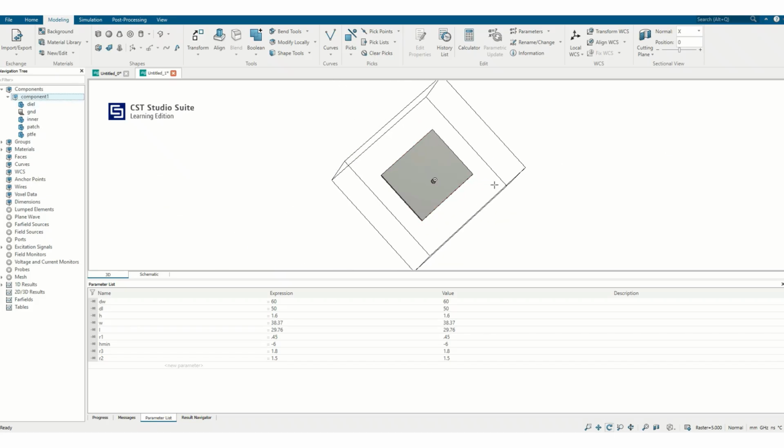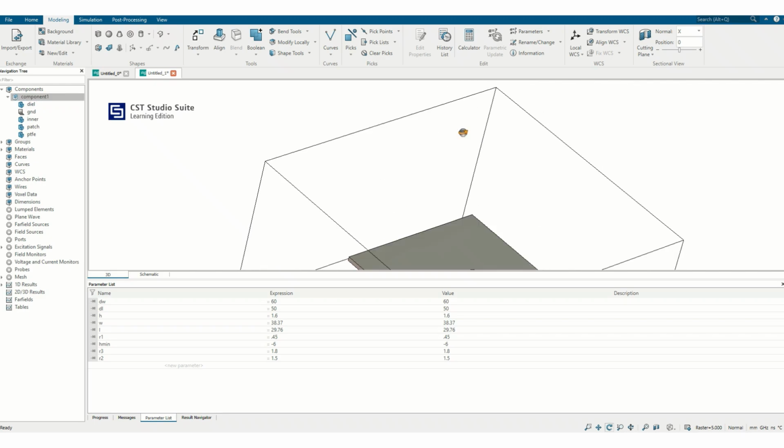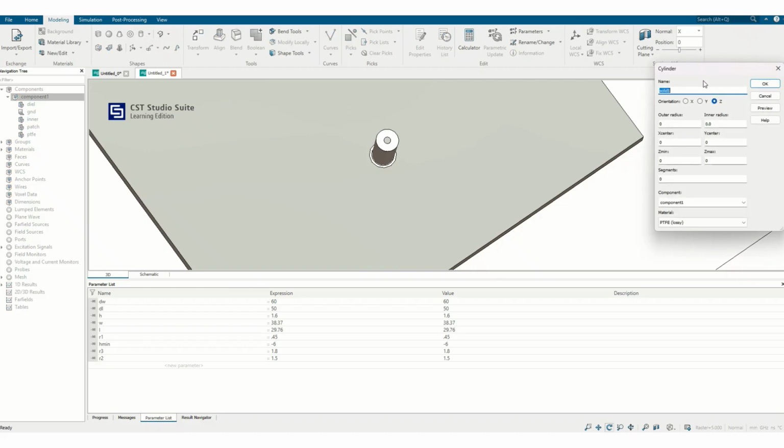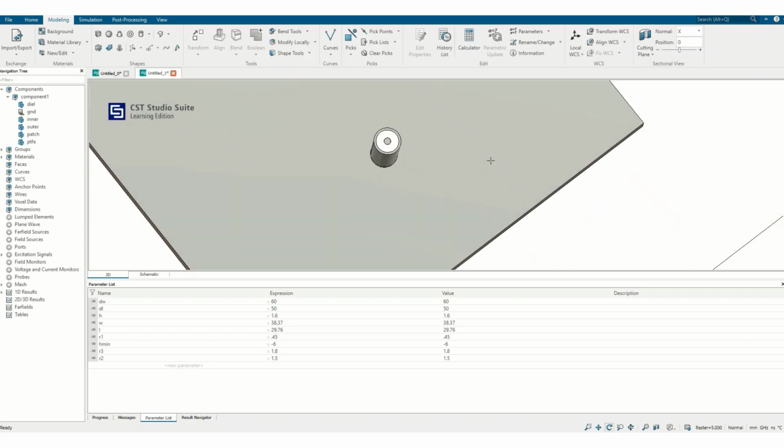Our next thing is to provide the ground plane so that it can be extended from here to here. So this is the outer conductor, and its radius is from R2 to R3. X center 0, Y center minus L by 4. Z minimum is from H min to 0, this position. And this material is PEC. So now we have that one. Okay.